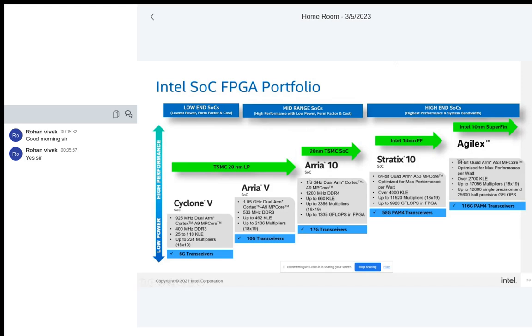What needs to be noted along with this, when you say it has a general purpose CPU? That is correct. It is an FPGA, so definitely it will have logic elements, that is adaptive logic modules. It will have memory resources, that is fine. When we were expanding the diagram, we had the FPGA which hosts the CPU inside. That makes sense because that CPU operates at 925 megahertz, 1.05 gigahertz, 1.5 gigahertz.